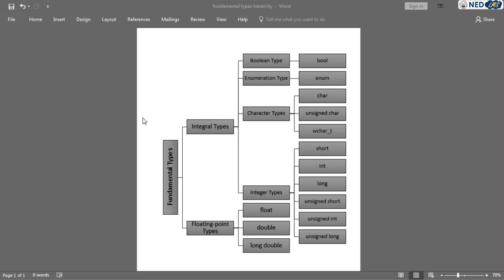In those environments where you have to use microcontrollers or small computers which have very little memory, and you have to control some physical processes such as some industrial processes, there you have to be really careful in using the type of variable, because let's say if you want to store really small numbers, you really don't need to declare them as long, because it probably is going to occupy 8 bytes of memory. And let's say if you have 1000 variables of type long, that is 8 kilobytes of memory just for the storage.